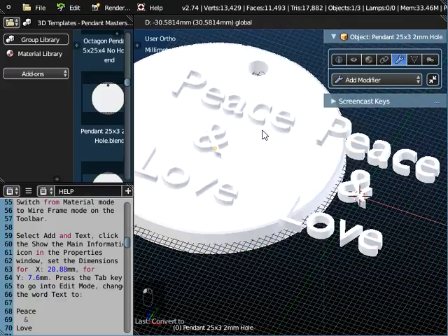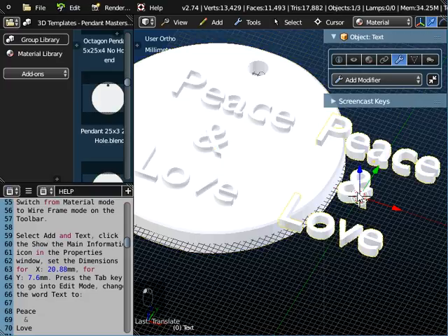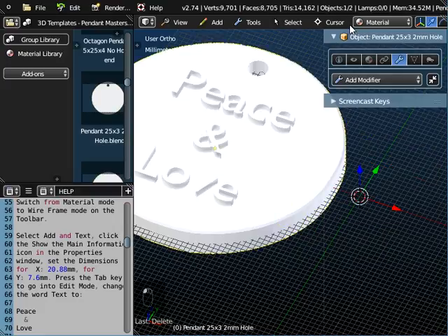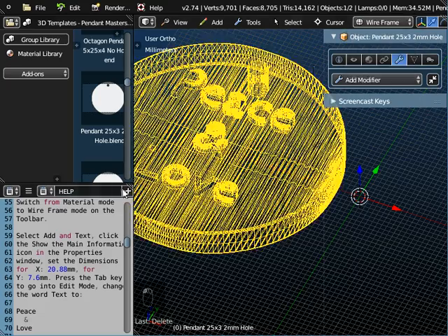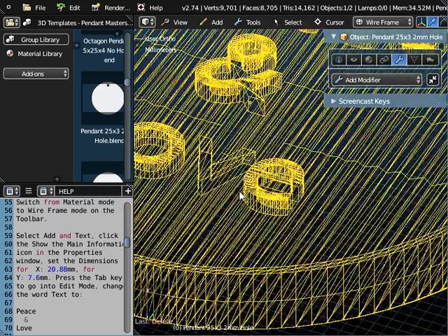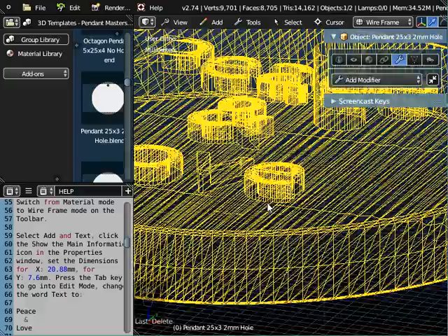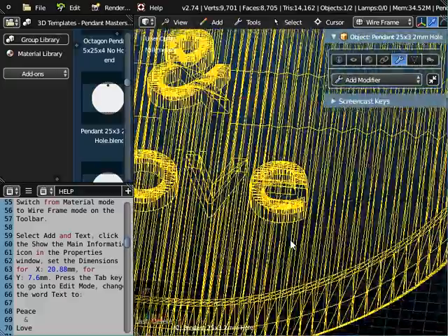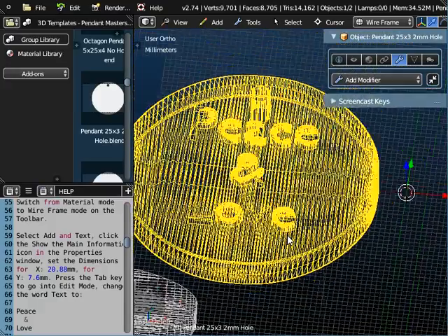If we move this out of the way, whenever we do Boolean operations, we're always left with a duplicate of one of the objects. So what we need to do is to highlight that and press X on the keyboard to delete it. If we look at this finished object now in the wireframe mode, those grey bits inside the object have been deleted by the Boolean operation. They're not there anymore, and we've now got almost a perfect mesh.